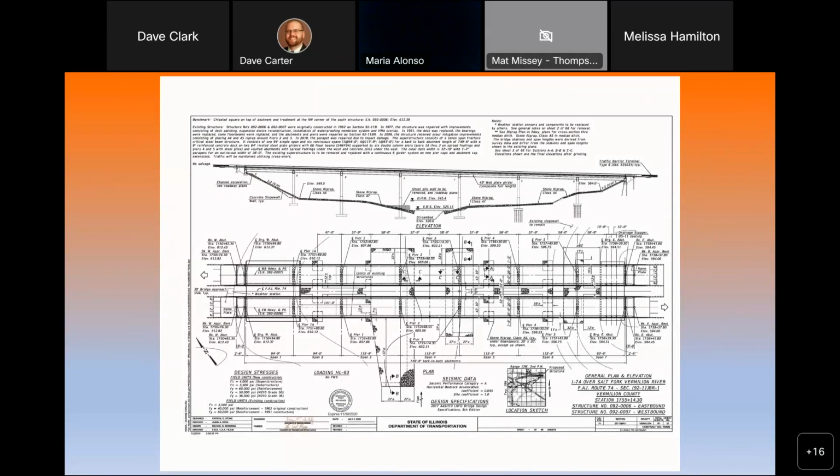There'll be a plan for each pier, one for each abutment. And those sheets give them all the elevations, and show the quantity of concrete, the quantity of rebar that may be needed, or other materials, riprap, for example, that they'll put underneath the bridge in different places. What those quantities are will be listed on the sheets that follow. There'll be sheets about the concrete or steel beams that are being used. So there'll be a ton of information in the bridge plans, and like I say, those are usually toward the back of the plans, and they're usually inserted separately from the roadway plans.